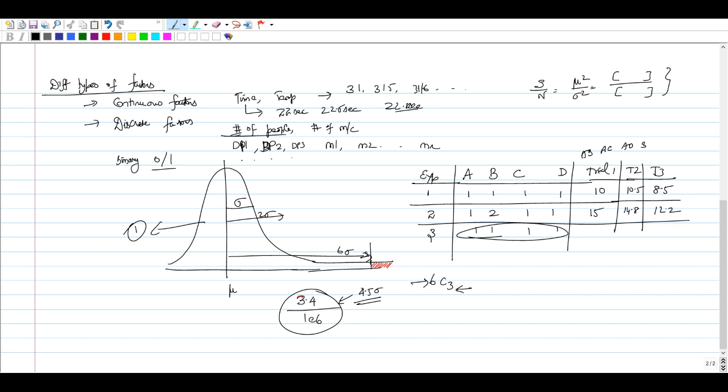That is because we have discussed this a number of times in the course. We want to use a factor of safety for the variability, because today you measured, it will be like this. Tomorrow you measured, it will be like this. Day after tomorrow there will be a shift. So there is something called a mean shift. You want to account for the mean shift, so you use a factor of safety of 1.4.